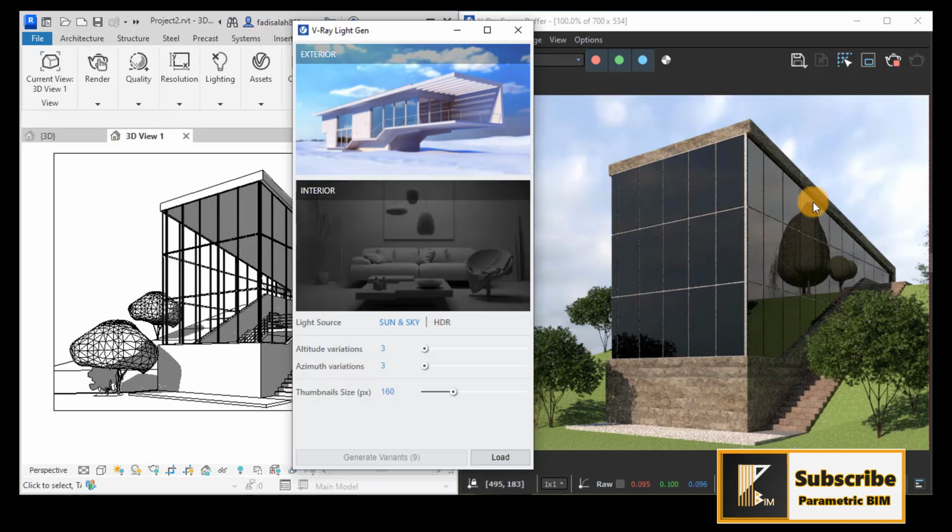But because we have an exterior view, we have to choose exterior here. So this will be the exterior that we have, and here we have the opportunity to choose the altitude and the azimuth variations, how many altitudes we want to generate with how many azimuths we want to generate.